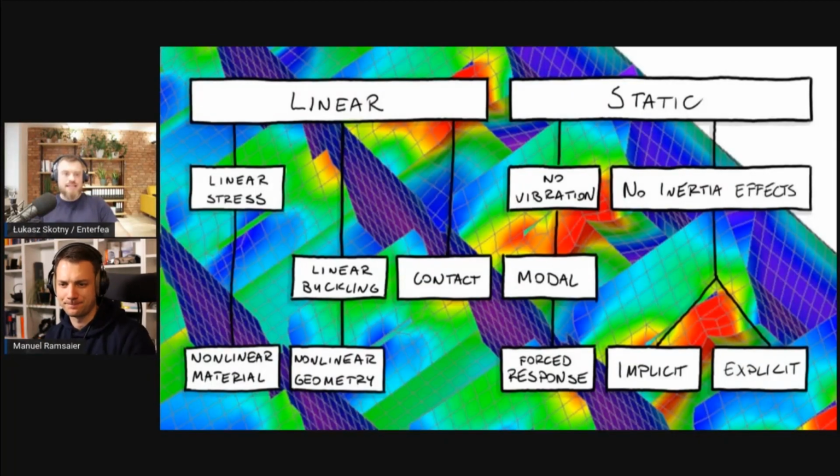But when it comes to the idea, it's very simple. You just tell your solver, look, I'm using this material. The actual relation between stress and strain in my material looks like this. Please take that into account in the analysis, press play, and it does it. If the material yields, for instance, you can't have stresses higher than yield, because the plastic redistribution will push the stress somewhere else. And you get a certain level of reality into the outcomes that linear analysis just can't give you.